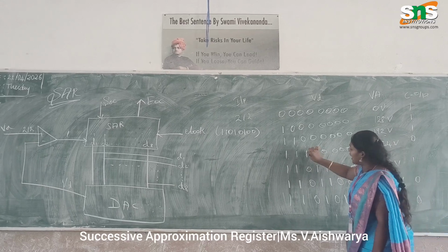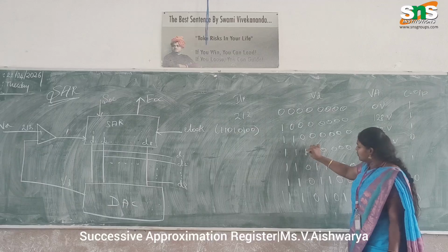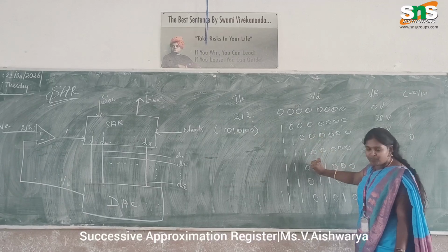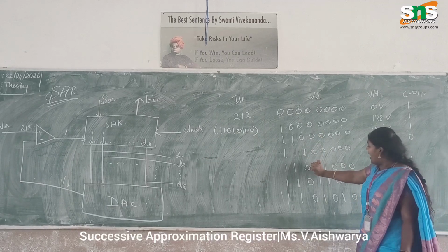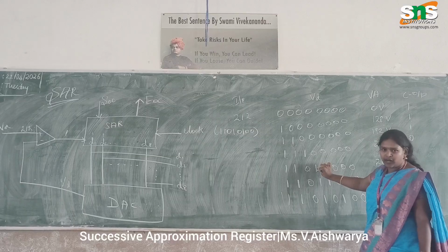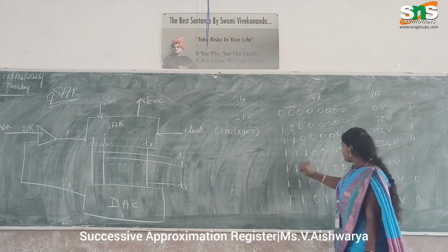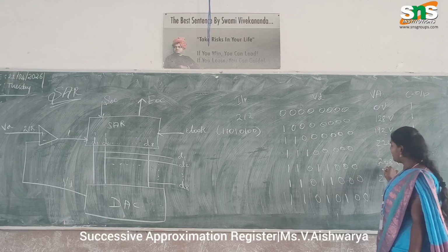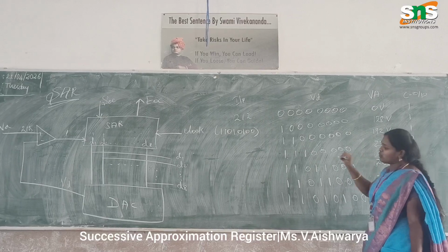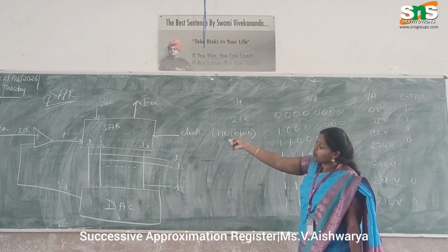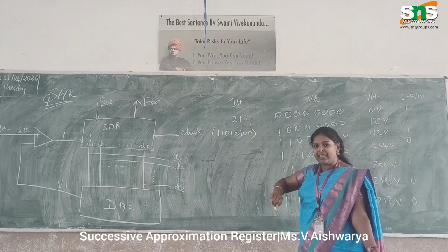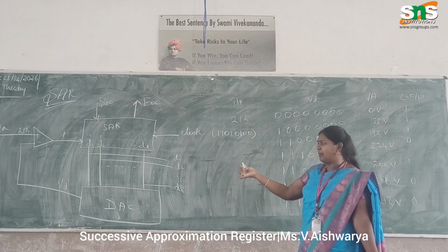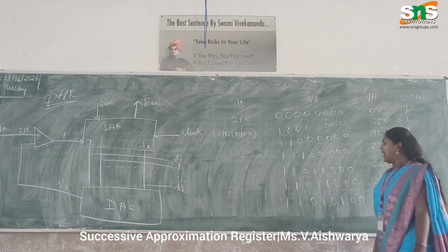That is, the third bit value is complemented, so the 1 is changed to 0, and the next bit will be turned on. The same process will be continued, and the next value is 208. The 208 is compared with 212. The 212 is higher than 208, so the comparator will be turned on and the next bit will be enabled.